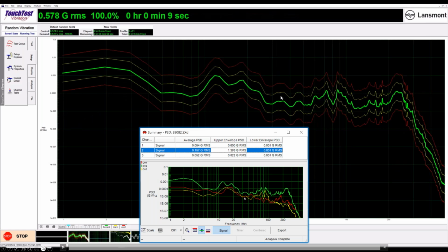There are 3 channels going on down here, but the green is the highest intensity, and that's because in this example it's representative of the vertical vibration that was measured during that journey. Once I export that, I can import it into my controller and be off and running, simulating the energy on average that occurred during that 1 day of measurement.